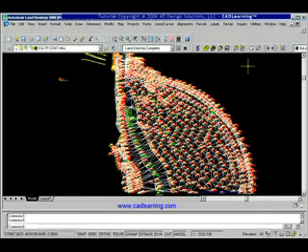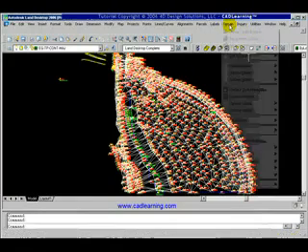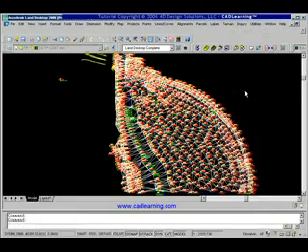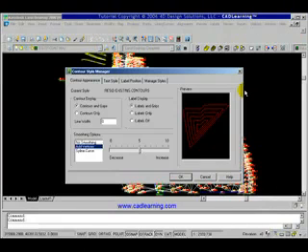Now we can go to the Contour Style Manager. We go back to the Terrain menu, select Contour Style Manager, and we have 4 tabs to work with. The first one is Contour Appearance. We have the option of displaying the contours with grips or just the contours. We're going to select contours only, as it makes it easier to edit the labels. For the label display, we will show both the labels and their grips.